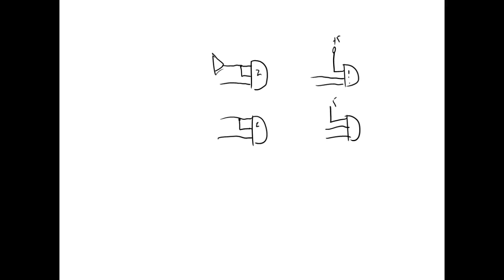Now, rule of thumb, if you don't know, is that most TTL gates can drive 10 loads. So if you're mixing 74LS and 7400s, you need to look it up on the data sheet. But normally, if LS is driving an LS, then the rule of thumb is 10 loads. But we're not going to do that. But this is one way we could do it, right?